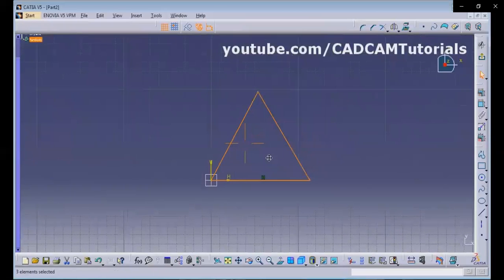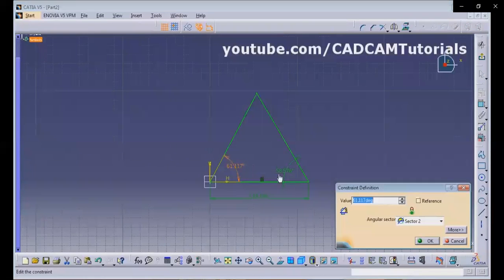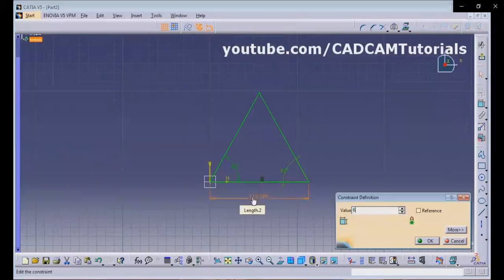Pan it down by holding down the scroll button and dragging the mouse. Then give the dimension using constraint, double click it so that it will give it continuously. And again angle between these two lines, click on these two lines and take cursor inside and click there. To come out, click on this constraint button, then double click, give the angle of 60. Here also the angle of 60, and the length is also 60.